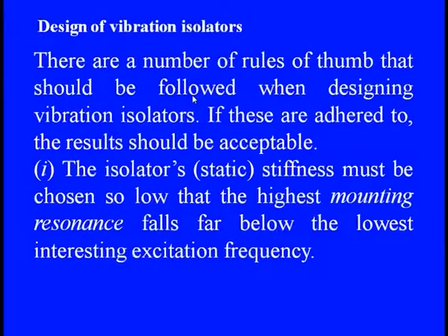First, the static stiffness of the isolator must be chosen so low that the highest mounting resonance falls below the lowest exciting frequencies. Whenever we keep the stiffness low, the mounting resonances are always lower than the exciting frequencies.